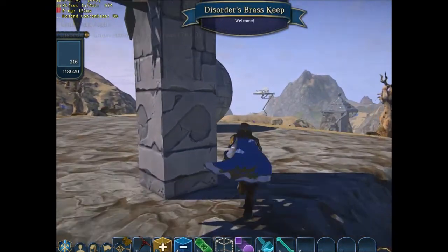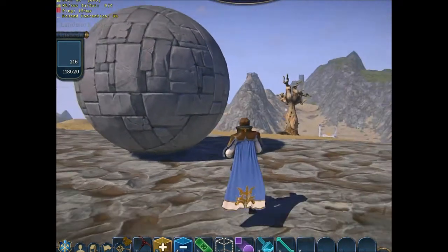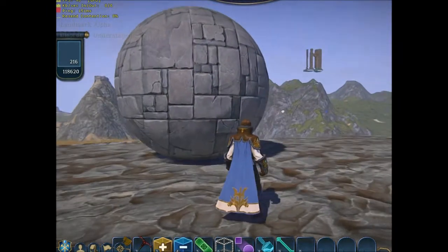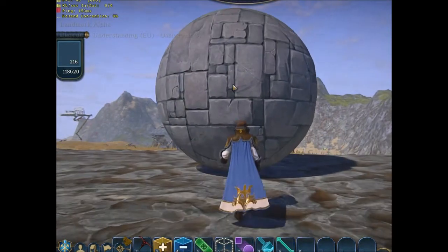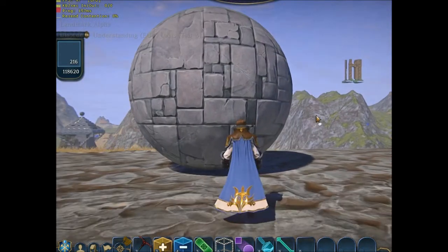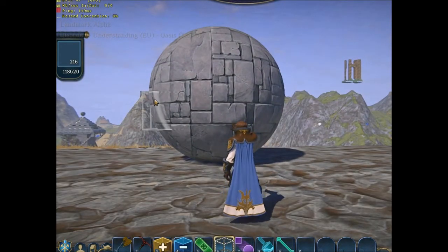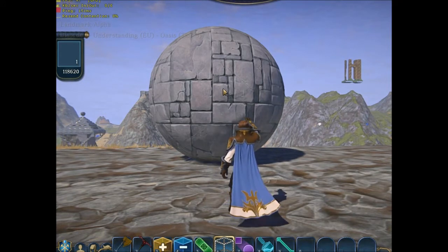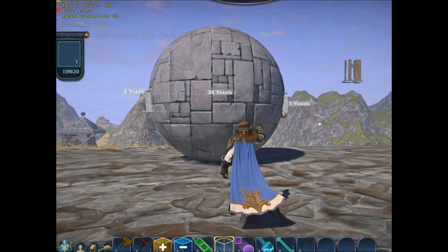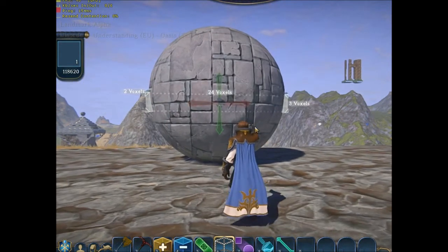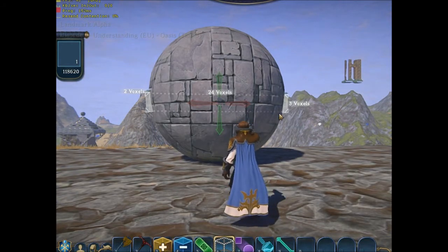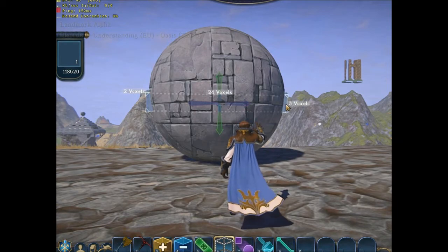So I already dropped down a sphere over here, and if you've seen some of my earlier videos, I showed how to make a donut, and that donut is used to stack to make a tower. The problem is this sphere's circumference is a little bigger around than I want for the tower. So instead of doing what I normally would do, which is cut out the very center of this sphere, I'm going to actually come down some and cut it a little bit lower down here, because the lower I am, the smaller the diameter of the tower will be.